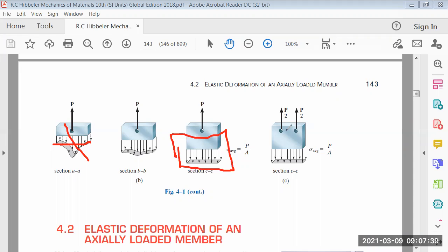Even if you look at these two forces, you have P over 2, P over 2. So Saint Venant says, okay, hence we have P over 2 added to P over 2, so it's the same as P. So it'll get the same amount of stress. Because if you get close to this point, the stress distribution might be like this. If this is our benchmark, a stress distribution could be like this.